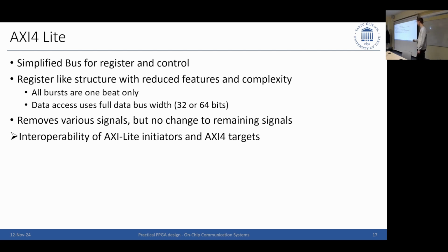And also nice, of course, and that's why I kind of like AXI, and I think is why it's also the standard. So almost everywhere it is compatible with AXI for full mode. This means that I can have AXI Lite slaves everywhere, and as long as I have the same signals and interpret them the same way, if the AXI master sends the correct values, it will perfectly interact with AXI Lite. So I do not need any converting logic or any adaptations to integrate AXI Lite into my overall AXI network.